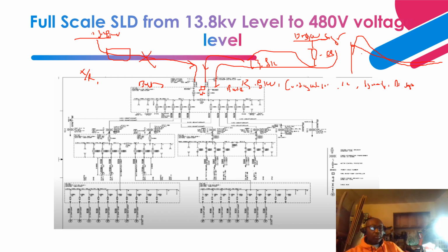Okay, so over here you have the incomer breaker, and over here you have an incomer. Definitely, you need an incoming breaker. There's a dedicated cubicle on the switchgear for the incomer breaker. Then there's also a dedicated cubicle for the tiebreaker. The rest are all cubicles in the switchgear lineup, as they call it. So you have bus one over here, then bus two over here, or bus A, bus B.